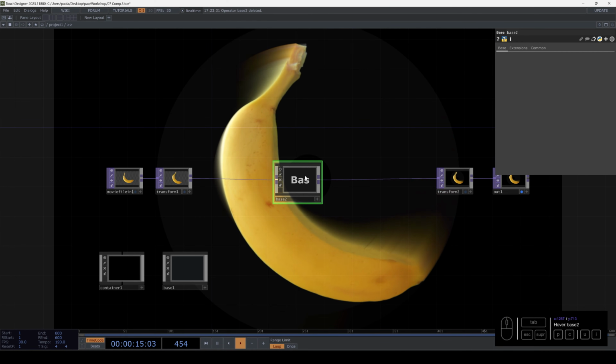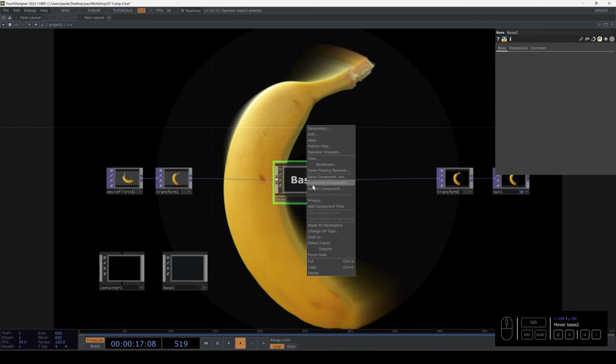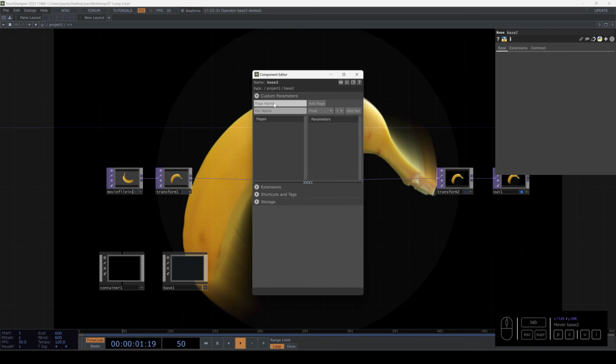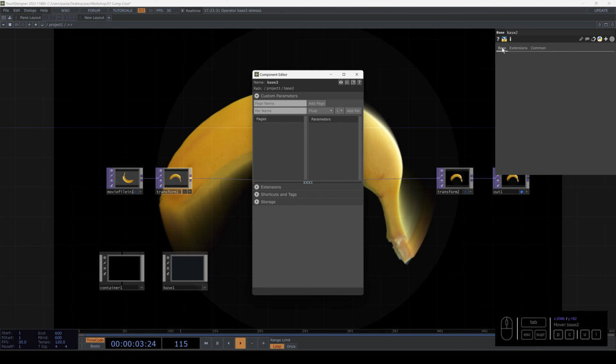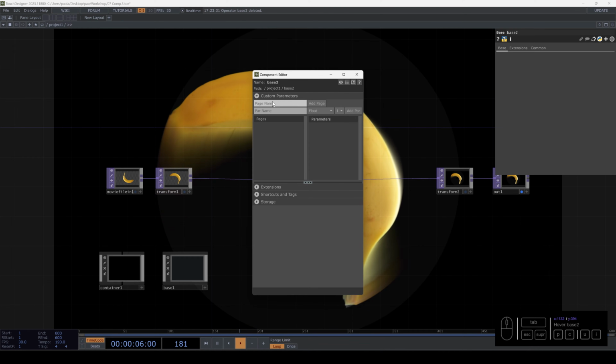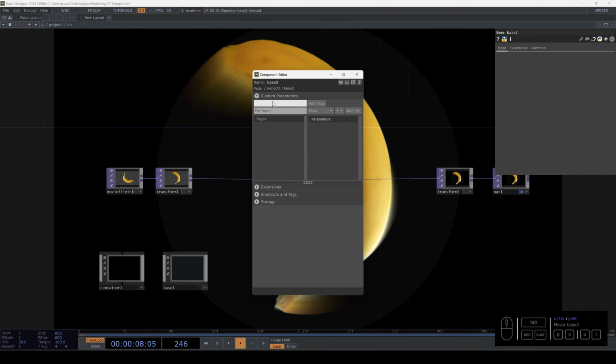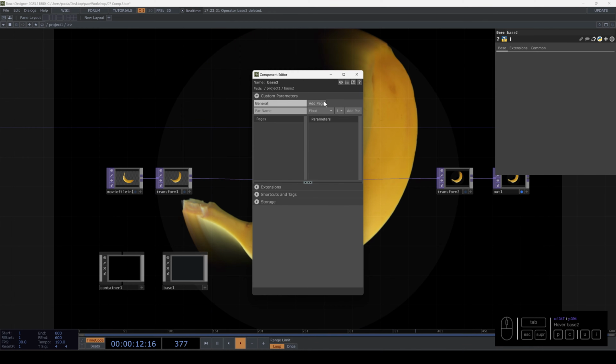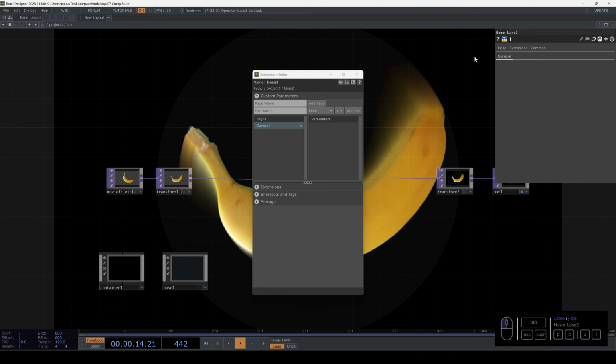I'm going to select this base, right-click the mouse, and select Customize Component. Right now we need to generate this tab. Right now we have Base, Extension, and Common. I'm going to create one, and the name will be General. Add. And we add this General, perfect.